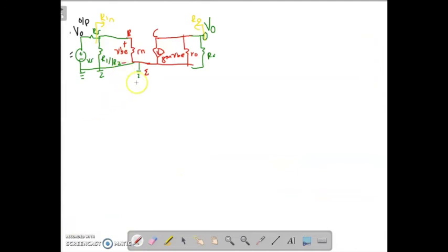Now let's start to derive again. As a revision from the previous video, it is the same. You should always start at your output. So the output is Vout equals I out times R out, Ohm's law, right? What is the current flowing from this output circuit? Here is plus minus, right?